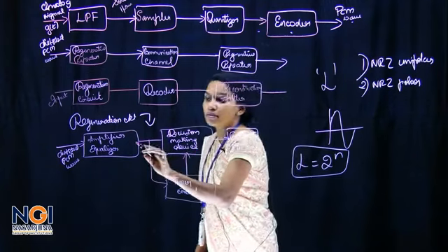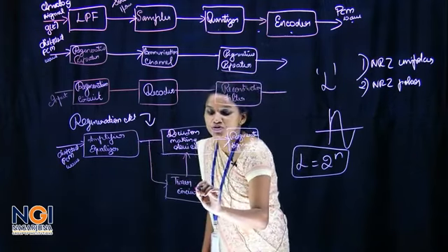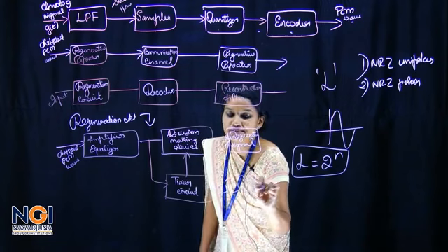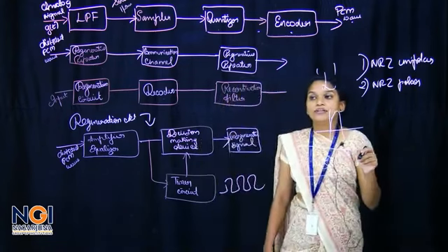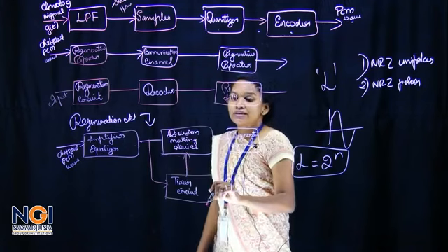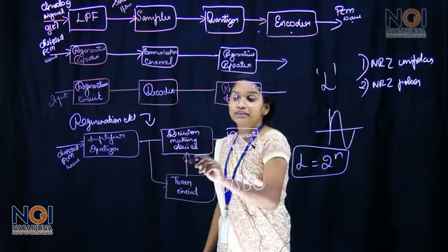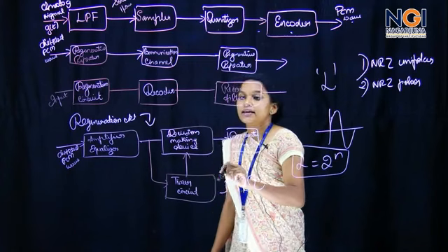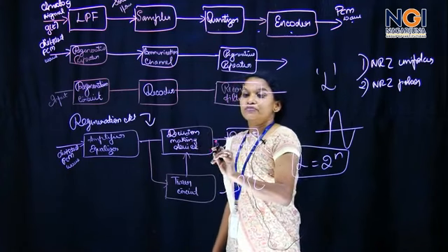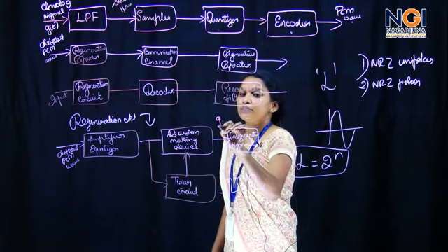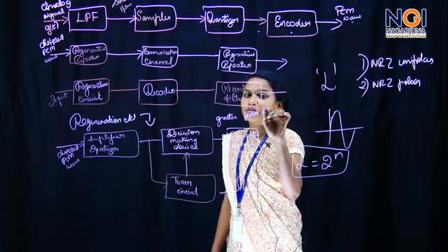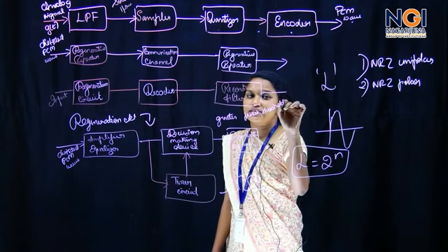The output of the amplifier equalizer is sent into a timer circuit, which produces a train of pulses known as the sampling waveform. Using that sampling waveform, the output of the amplifier equalizer is sampled at different sampling instants, and a threshold value is already set.